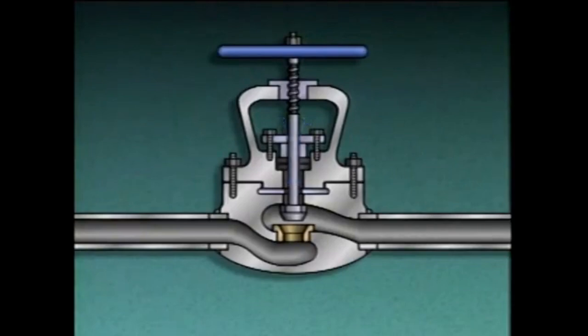The pressure applied to the packing by the packing gland is adjusted using gland nuts. The pressure is adjusted so that the valve stem can be moved as the valve is repositioned, but leakage does not occur around the stem.